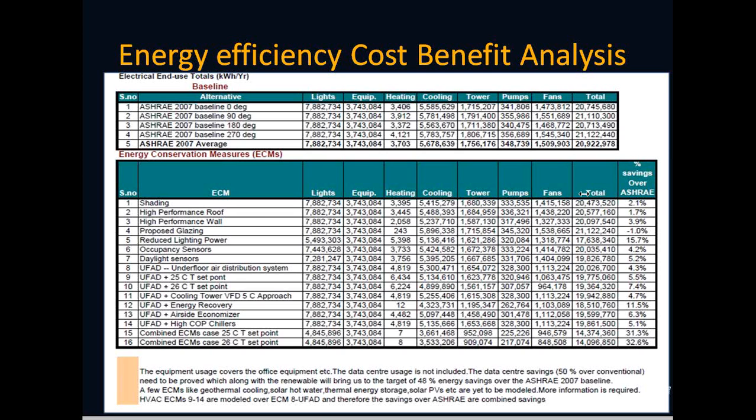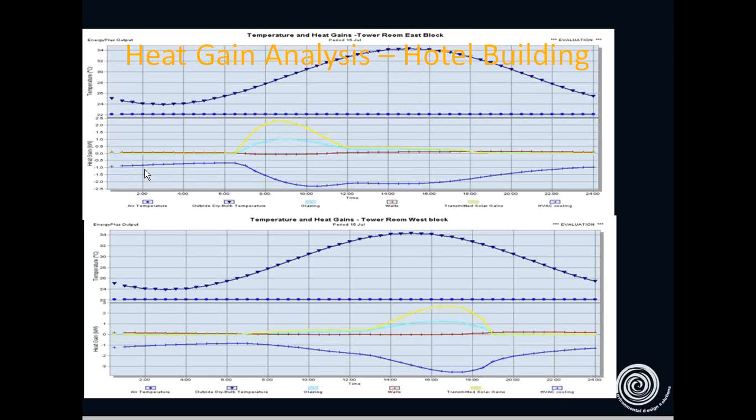This shows that thing, but you just watch. Sorry, this thing, the cooling load, the lowermost blue line. So you can see that here the east-facing rooms are having their peak cooling load at around 10 a.m., whereas the west-facing rooms have a cooling load at around 4 p.m.